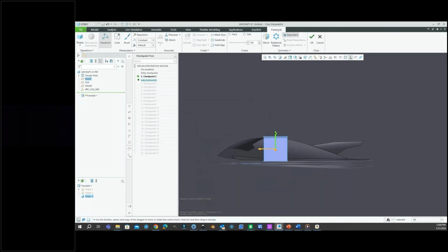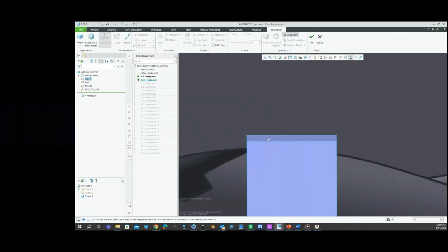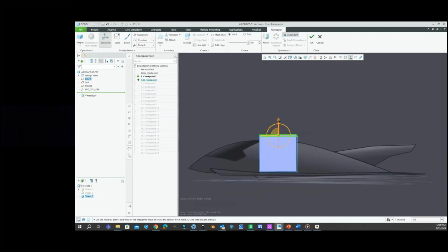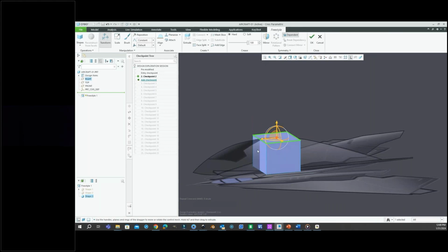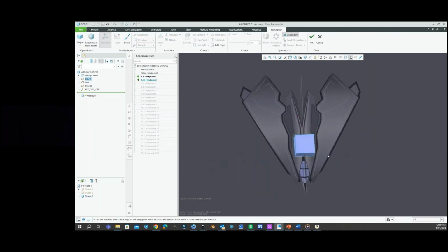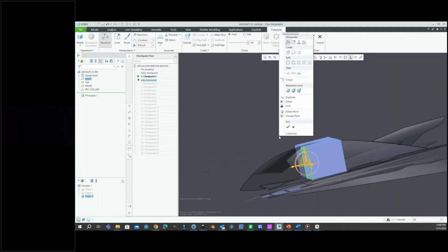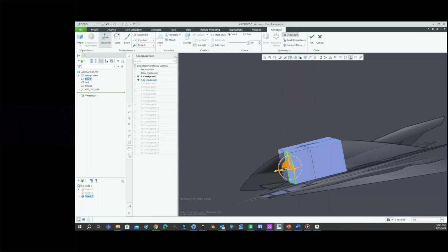So I would maybe start there, for example, and then move that face down. And then in the same way, I'm going to mirror. So I'll select the vertices on this side and then mirror using my right plane, and then start sculpting this, right? So I'll extrude and extrude again.